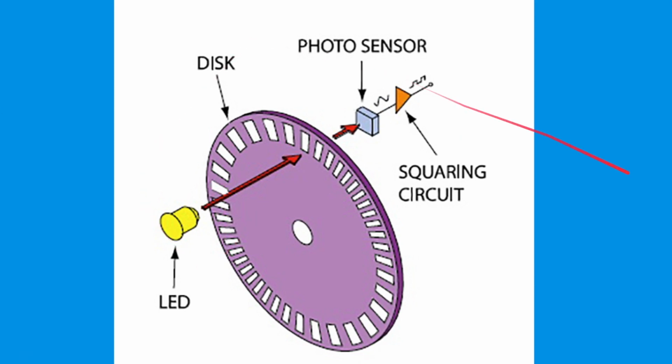So this is one type of encoder. This is an optical encoder. How it works is you have a disc with holes inside of it, and you have an LED light, and here you have a photosensor. Basically every time this turns, and these are a set distance apart, it can check, oh, it moved, let's say, 1 centimeter, because the light would shine through the hole and be read by this photosensor. There are other types of encoders too, such as magnetic and mechanical.